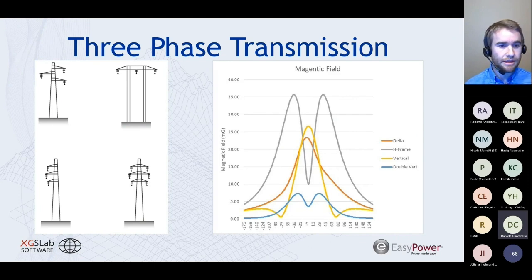One thing to note is there's often some sort of maintenance process associated with transmission lines. So one of these transmission lines may be out of service, or one of the circuits may be out of service on this line, and that can result in an analysis that would initially start out as the double circuit configuration, but then be in a vertical configuration when you have a single outage on your system. And this is all during steady state operation.